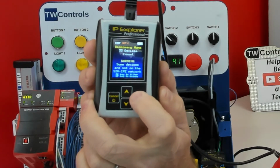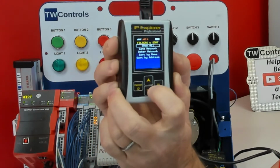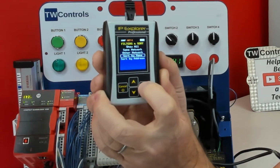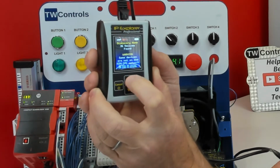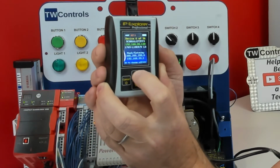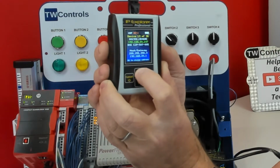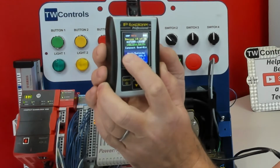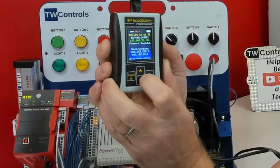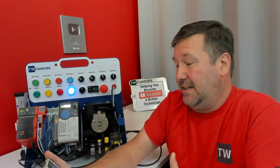And then in this particular IPE's case, we actually have a filter option. So we're going to click OK. And then I can sort by name because I know this is a Compact GuardLogix PLC. And I'll click OK. And then I can hit the up arrow. Got some 1756, got a 1766, 1769, some 2080s, a 5032, and finally come to a Compact GuardLogix. And even here we have 2 of them. So we would need to distinguish which one of these actually it is.